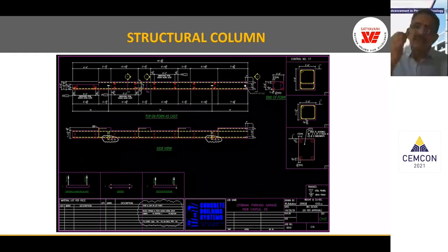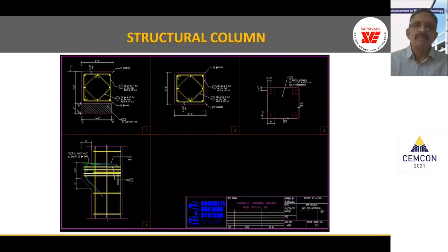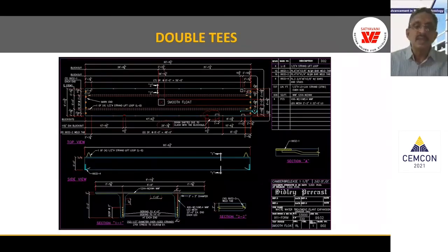So, the modular precast concrete elements for buildings: I'm showing some of the sample detailing that we do, the level of detailing that goes into the precast which is required. You can also see the stripping, stacking, and handling stresses that we show in the drawing itself, so that in casting and handling they use the same method of casting, stacking, stripping, and transport. And these are all the bar detailing, which will almost go into 1:1 scale to check the fittings and clearances in the joints and reinforcement.